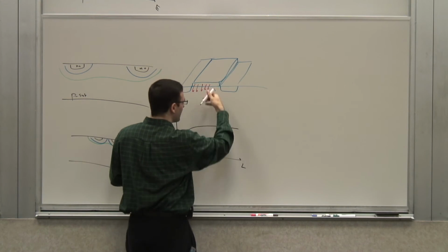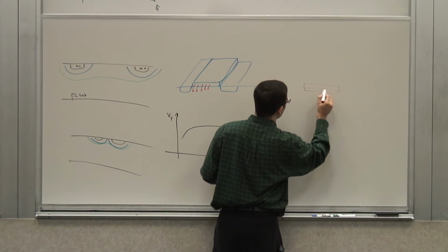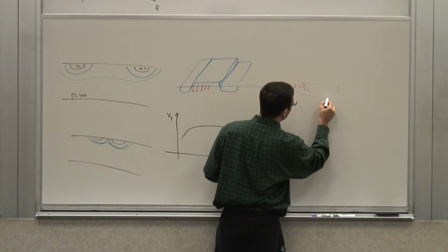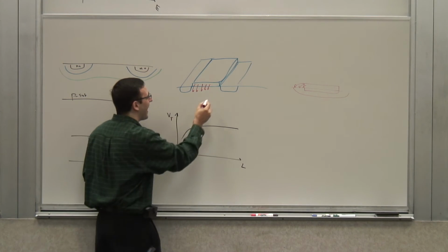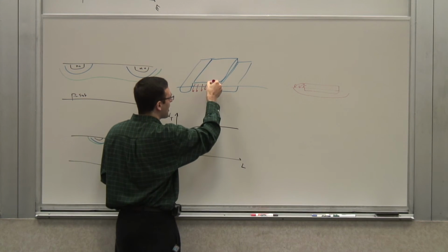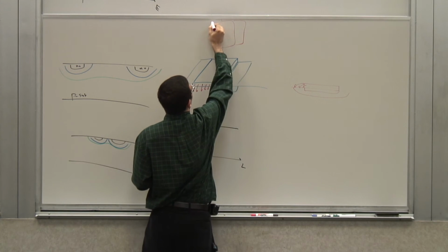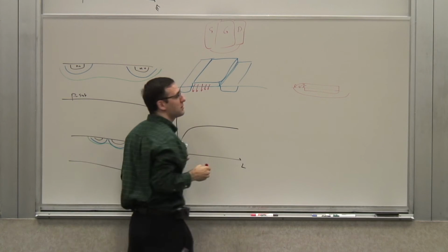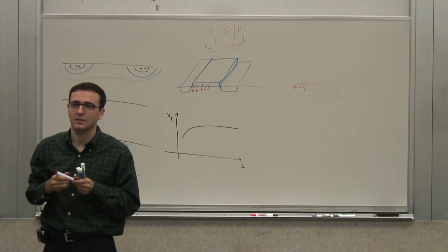So if you look at it from the side, this is the gate, this is the drain and source, there's a little bit of electric field here. Now, the depletion region is extended laterally in this direction too. So you have a little bit of depletion region outside the transistor. If you look at the top-down view, this being the source, drain, gate, you're forming depletion region here and there because of this extra electric field.